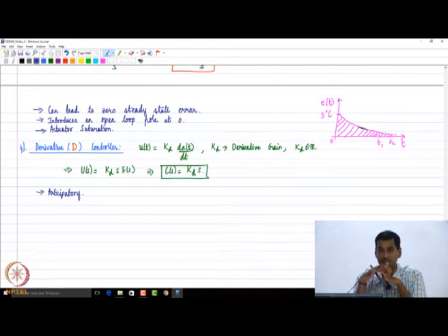So because as soon as the error reaches a certain value, it remains constant, the controller won't be able to track it. In other words, you will see that the derivative controller will not take any action if the error reaches a constant non-zero value.